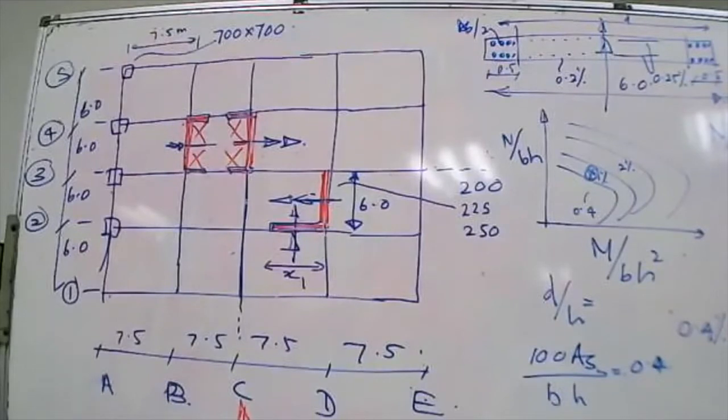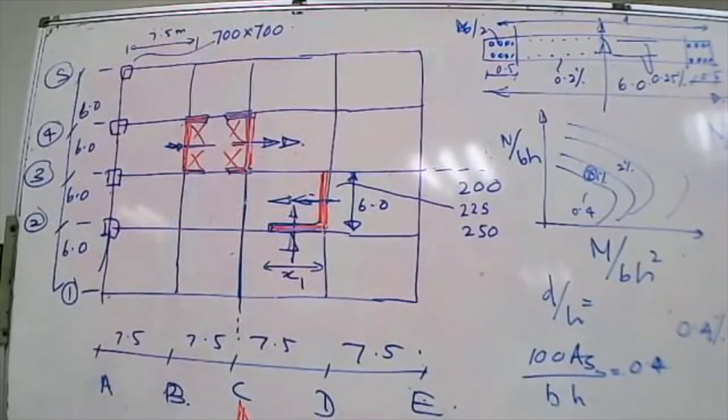I will consider the foundation design much more seriously than the design of the superstructure, because finally all these loads should be transferred to the foundation. Now we have a big problem. The problem is, do we need a pile foundation or a raft foundation? That is a big question. Because sometimes a pile foundation might have only a few piles, but it might cost a lot of money because pile foundation means a lot of mobilization. So we might have to consider a raft foundation, although it's a 10-story building.